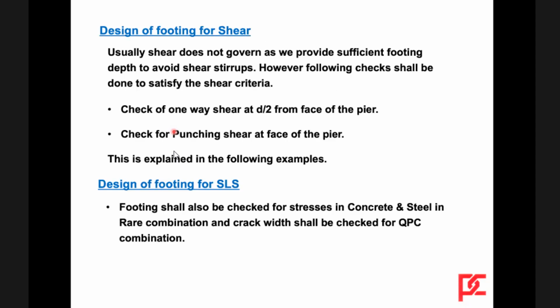Then, apart from this bending moment design, footing is to be checked for shear also. Most of the time, we use the depth of the footing such that it is safe without any shear reinforcement. But sometimes you may require shear reinforcement in the terms of shear stirrups. Usually shear does not govern, as we provide sufficient footing depth to avoid shear stirrups. However, following checks shall be done to satisfy the shear criteria given in the code.